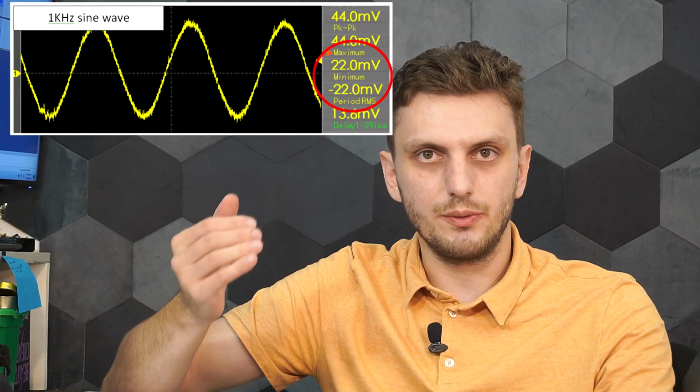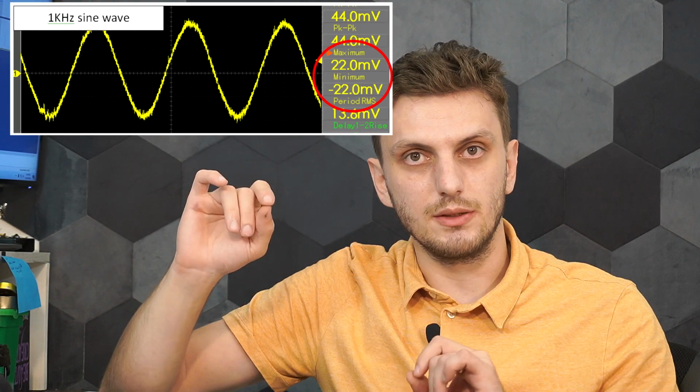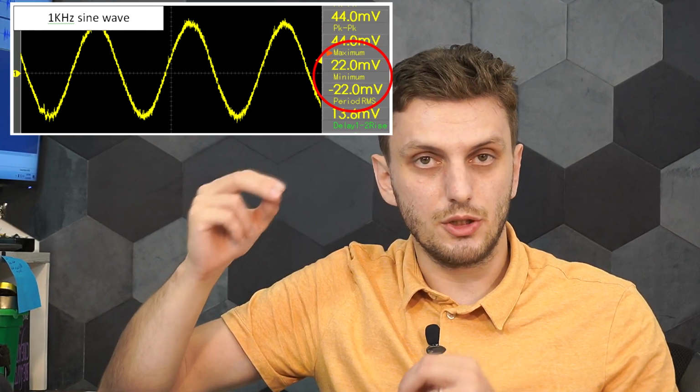Now, before moving on to the actual circuit, there's one more thing that needs to be mentioned. And that is that, unlike a clean sine wave, the sound coming from the guitar when you play a note is a combination of multiple sine waves that end up being a non-symmetrical signal. So when you reference a normal sine wave around its average point, you will have two symmetrical signals, which are granted phase shifted, but the two peak amplitudes are equal.